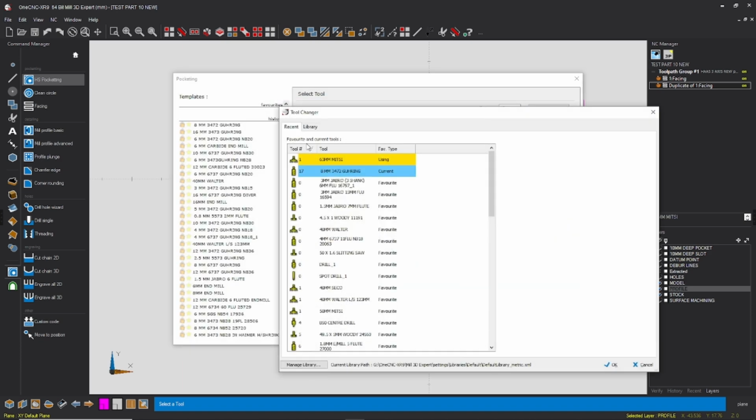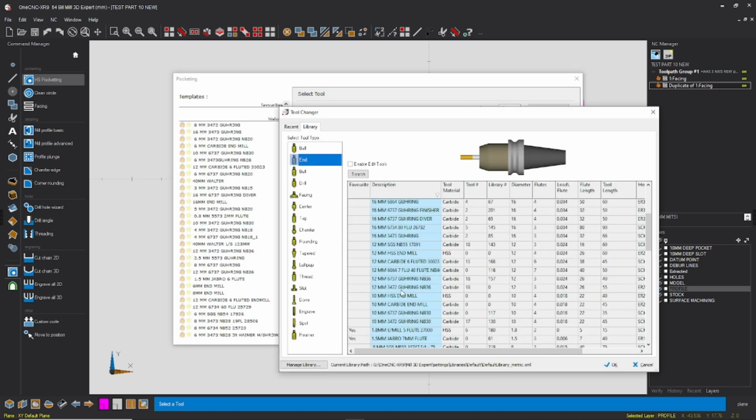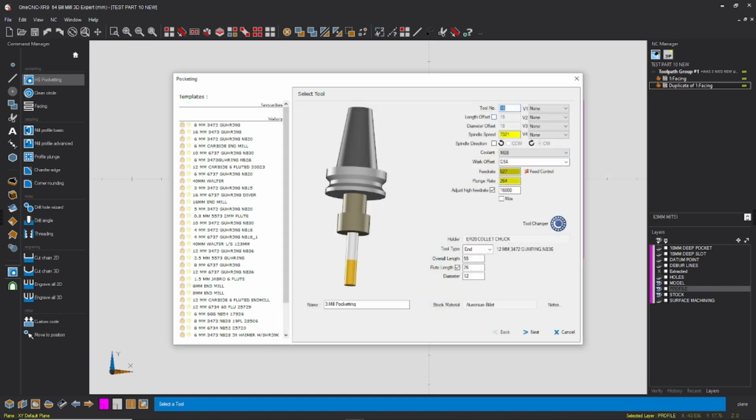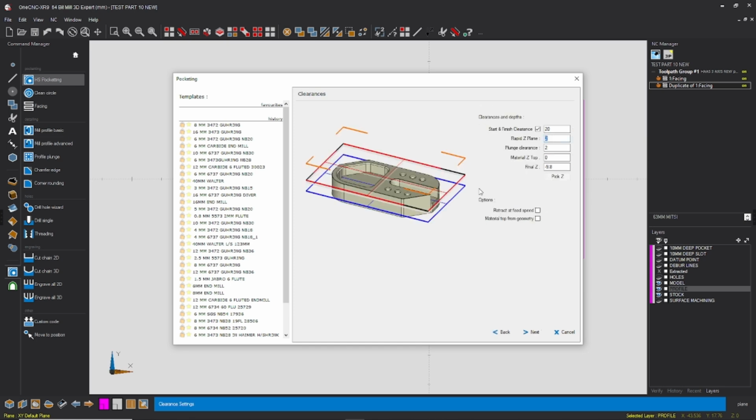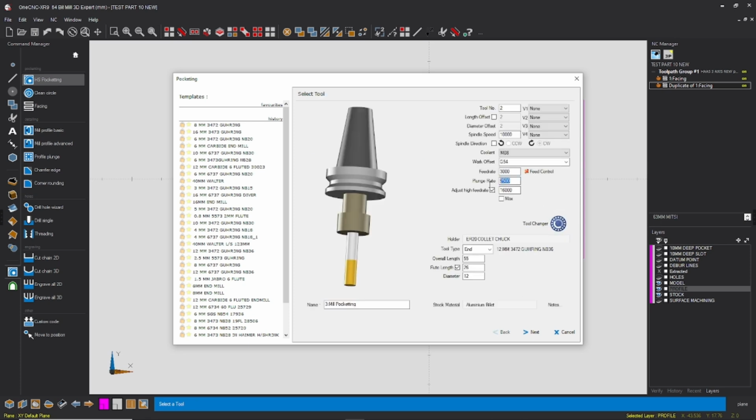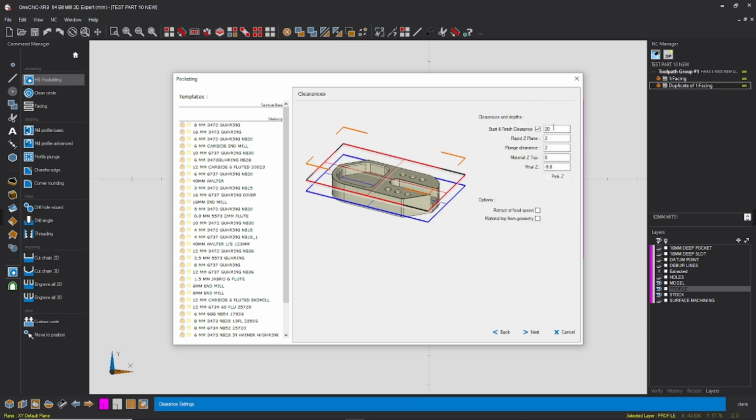Let's find a tool capable of doing what we want. So let's find a 16mm carbide end mill. We'll call this tool 2, and we'll spin it at 10,000. That'd be number 1 here, by the way. I've just renamed it to M08. G54, go 2,500, yeah, 3,000 actually. 2,500 plunge feed. Remember, I won't plunge cut nothing, so that's why my plunge feed is a bit excessive. You know, we're not going to actually plunge cut, and I'll show you why.